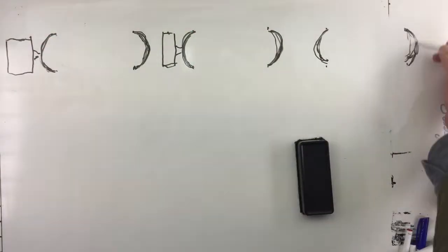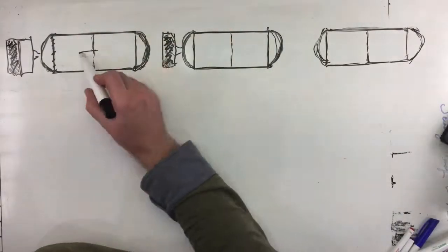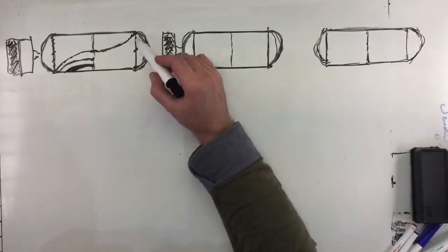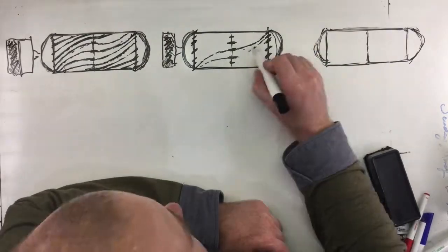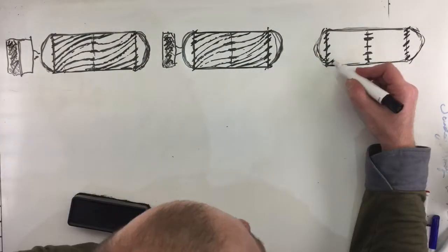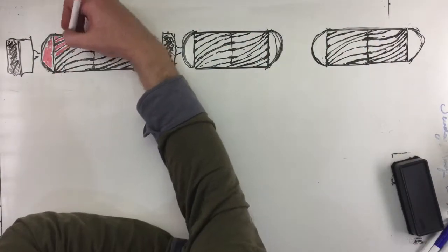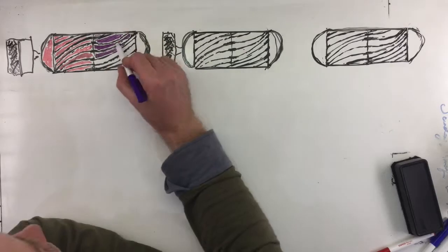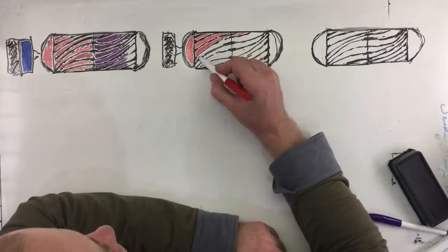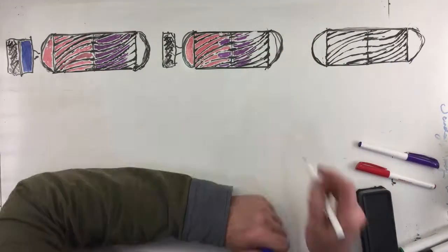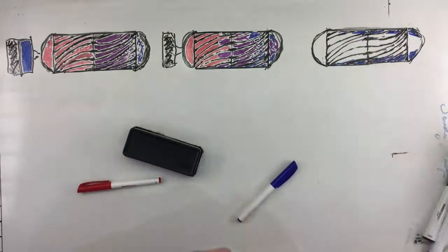Now, as the steam condenses into liquid water drops on the surfaces of the ship's interior, the drops will be accelerated away from the axis of rotation around the central shaft, to form a pool of water that jackets the ship's interior. Let's say that with the right kind of spacing and spiraling of our baffling and the right kind of coolant circulating through it, we can design a system that is so good at condensing the steam as it passes by that it condenses virtually all of it into liquid water that flows into the pool.